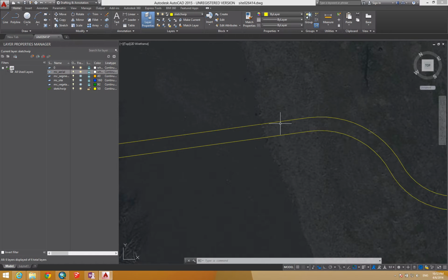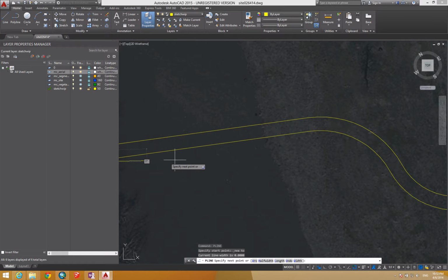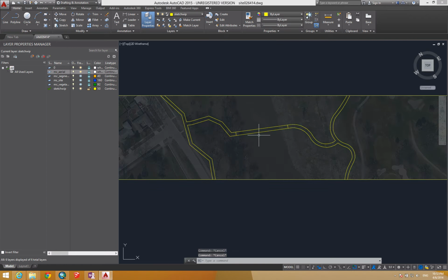But you've also got the shift right click. Let's do that on this side. Polyline. Whoops, I typed NEA out of force of habit, so let's do that again. Polyline. I will shift right click, and now I can select nearest. And I don't know why it's snapping back to that. I don't want that, so let's hit escape. Let's do it my way. NEA, nearest right about here, and then PER for perpendicular to there. Hit escape. So that gives me a perfectly rectangular area represented by those starting and ending points. And you'll see why that's important when I go back to SketchUp here in a moment.